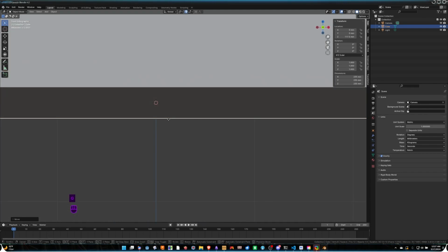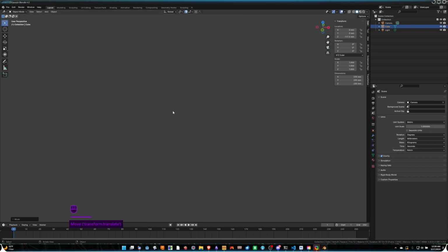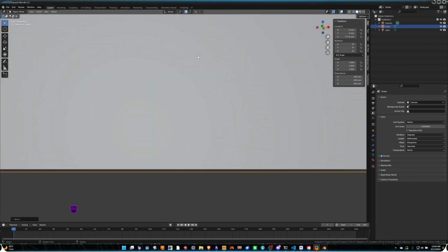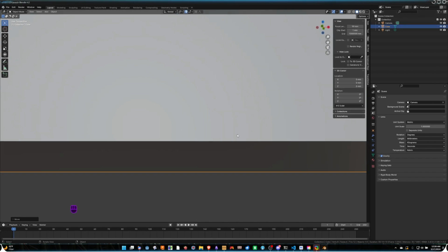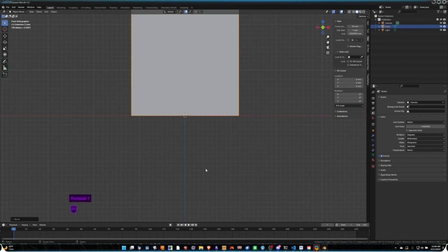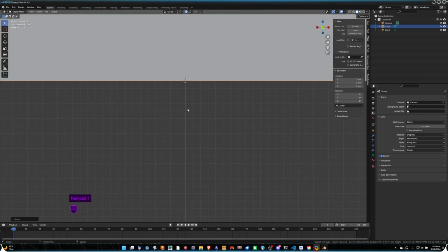And that's the perspective shadow. You can move this up, back down, and you can see that the perspective shadow is intersecting. It's actually the near clipping plane that's intersecting with our view. What we can do is go to View and set the clip start to 1 millimeter. If we hit 1 again, we can zoom all the way back in.